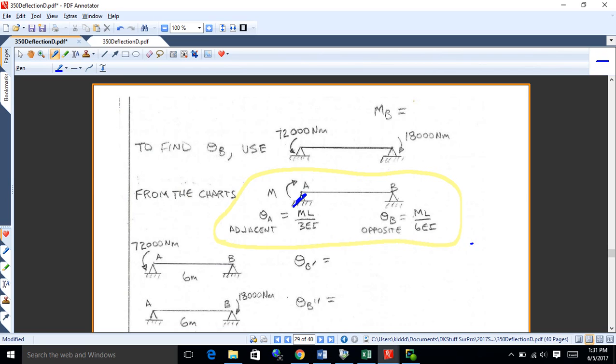All right. Now here's how I think about this. I think of taking what I call a T-bar handle. Have you ever seen like a valve wrench? They've got T-bars on them. And then I'm going to turn the handle clockwise. If I turn that handle clockwise, which way will that thing bow? Yeah, it's going to go down, okay? But the effect will be more pronounced again next to where the load is. So that thing will bow down pretty dramatically, and then it'll kind of recover and come up like that, will be what it would do.